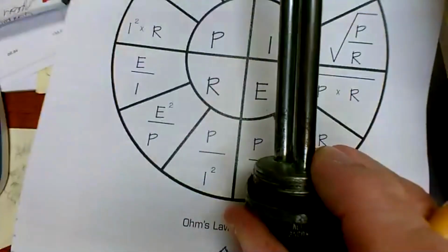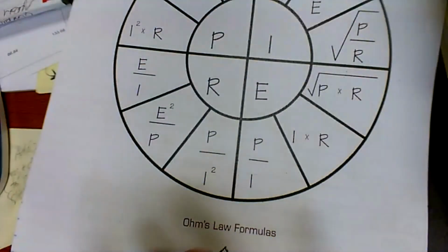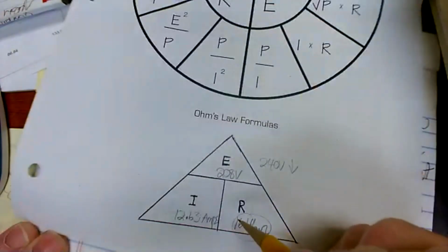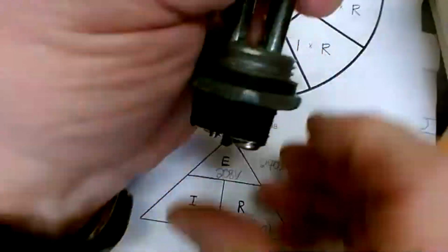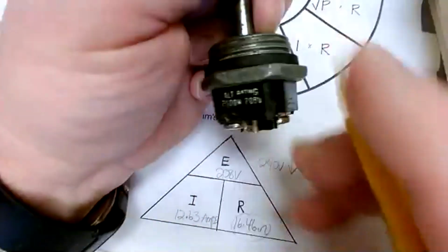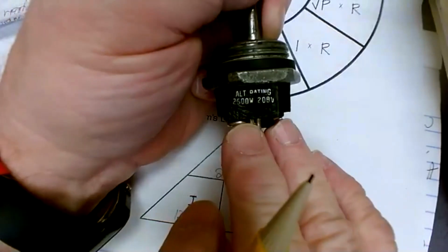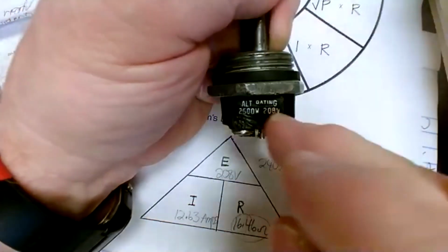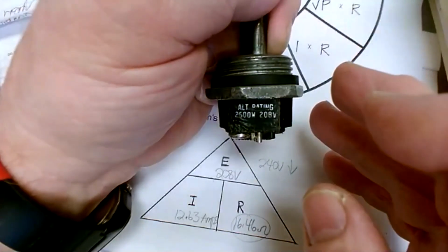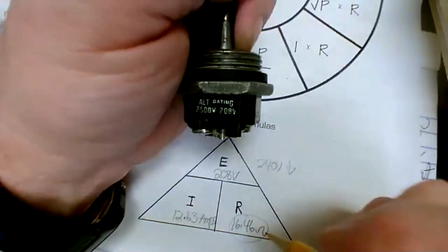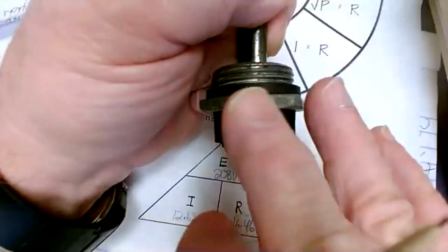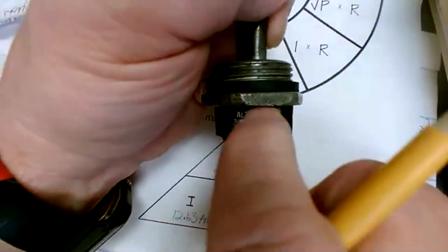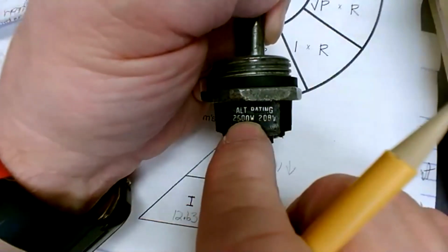Okay, so anyway, that's as close as you can get it right there without actually measuring. The way you would know for sure would be to actually put 208 on here and measure the amps. Then you could use the real amp draw to calculate the real ohms at that lower voltage. That would be a way to really verify this. You know what I mean?